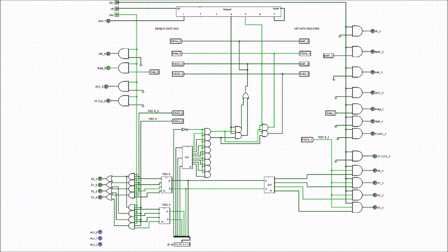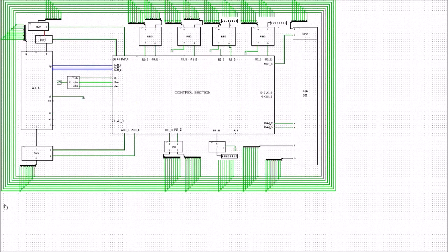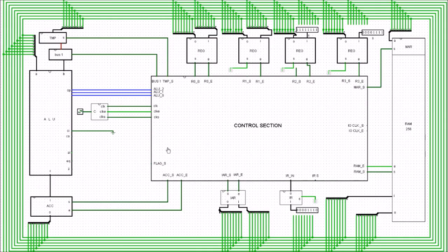We'll go to the top level, and we can see that the RAM has been enabled. We've taken the contents of that RAM address, 15, and put it onto the bus. Now the next thing we're going to do is set it in R2. So we click on the next clock pulse along. That's the set here, and you can see the set has gone high. In effect we're taking that value on the bus and putting it back in here, and it's all ones that we're putting back in.